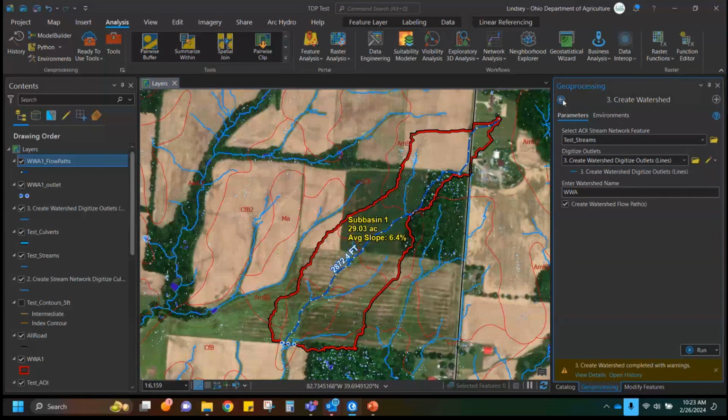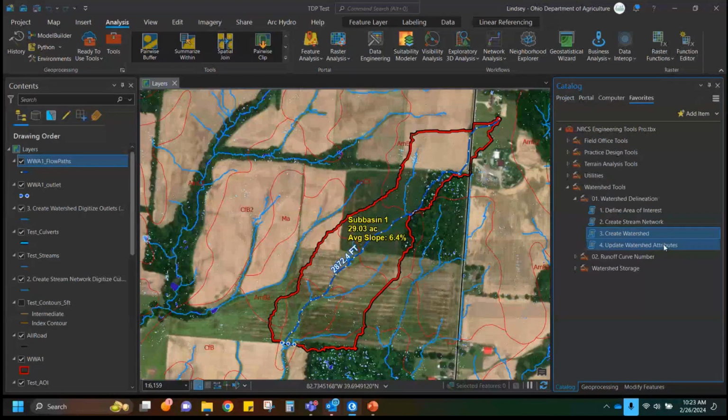Okay. So here's the fourth step. I don't think I might have used this once ever while designing waterways. But the purpose of it is if you know that there's a mistake in the watershed and you know how it actually flows, say the DEM isn't picking up on something that you know is there, you can go in and edit the shape of the watershed.